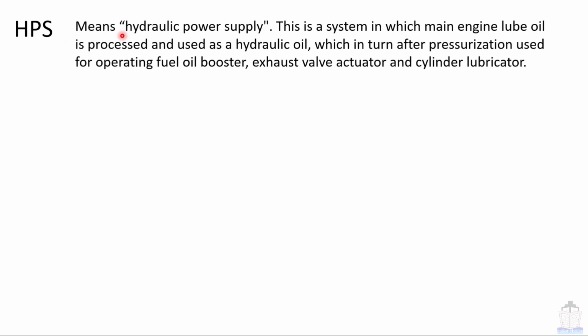HPS means hydraulic power supply. This is a system in which main engine lube oil is processed and used as a hydraulic oil, which in turn, after pressurization, is used for operating the fuel oil booster, exhaust valve actuator and cylinder lubricator.